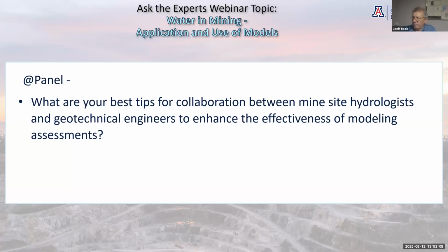Yeah, Jim and Jeff are absolutely right there. Often the geotech and the geology team get much more budget for drilling holes in the ground than the hydro teams necessarily do. And so getting that integration and making sure that once you're buying a hole in the ground, you're getting as much information out of that hole as you possibly can. Making sure that you're extracting all of the value and don't grout holes before you put things like VWPs in them. So making sure that there's that interaction with the geology and the geotech teams as early as possible is really important.